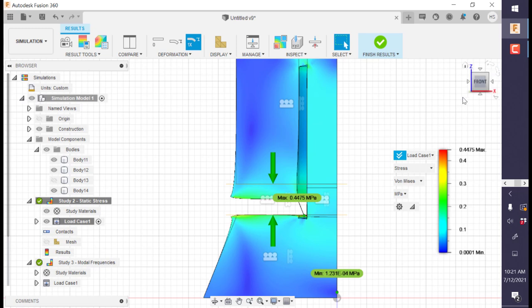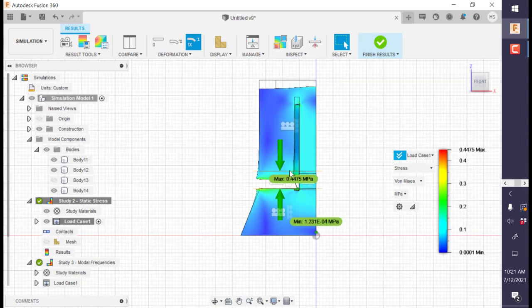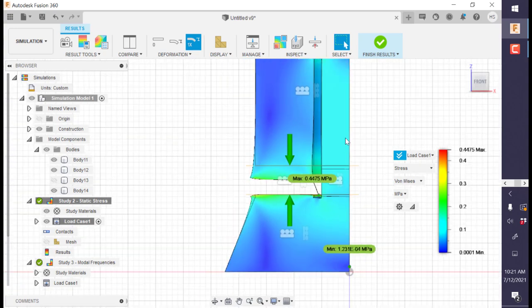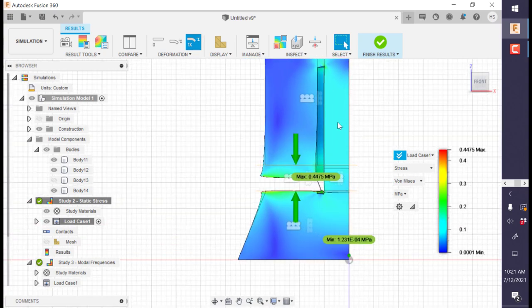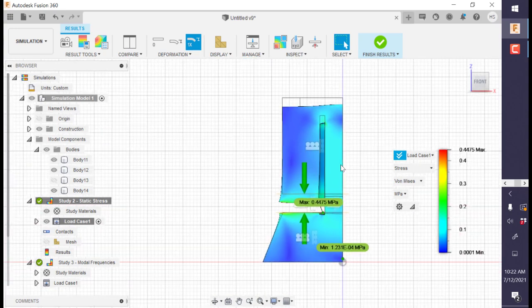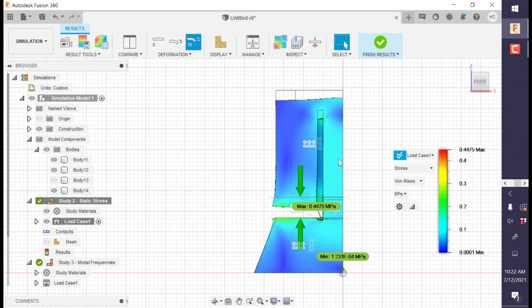Due to the DC bias force applied in this type of device, it's not held together necessarily like glue, although there is glue or epoxy applied. Whatever direction the piezo goes, whether it's stress or compression or tension, the center bolt will follow suit. For such a device, if you make the center bolt smaller, you'll have less to push against, so you'll have a more free vibration of your piezo.